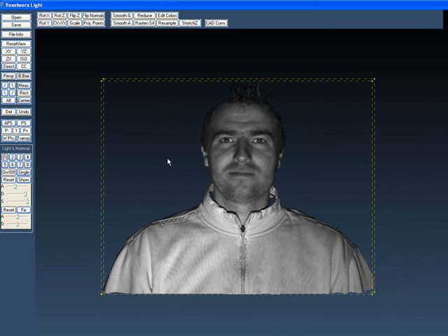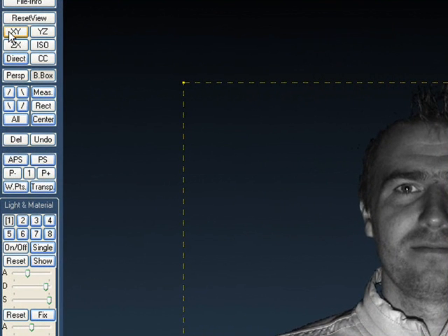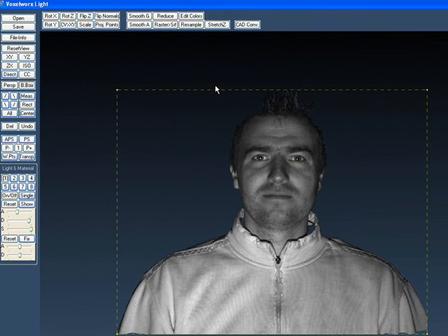Now what we want to do is clean out the file and choose a cutout of the file for the cut conversion. So first we reset the view to XY, and now you basically have different selecting methods. You have rectangular, which looks like this. You always have to hold down the control key in order to start the selecting, and then with the left mouse button held down, you can drag a box, for example like this.